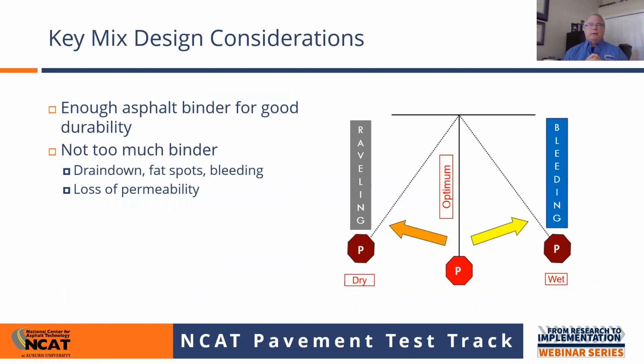One thing about an open graded mix, when you're doing a mix design, like everything else that we deal with in the asphalt world, there's this pendulum that we're dealing with. In an open graded mix, you want to make sure there's enough asphalt binder for good durability, so it's going to last longer. Okay, we want that. However, if you put too much binder, you're going to have drain down problems, which would be a construction thing. You'll have fat spots in the pavement. You potentially have bleeding, which creates another safety problem. And you also have a loss of permeability.